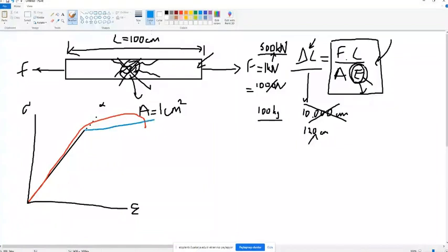But we will try to approximate like this. Here is the first modulus, which is theta, which is giving the E, Hooke's law and Young modulus. What is that? Sigma over epsilon. But here, there is another modulus. Maybe we can say theta 1 or alpha beta, it's not important. This is called tangent modulus, E tan.